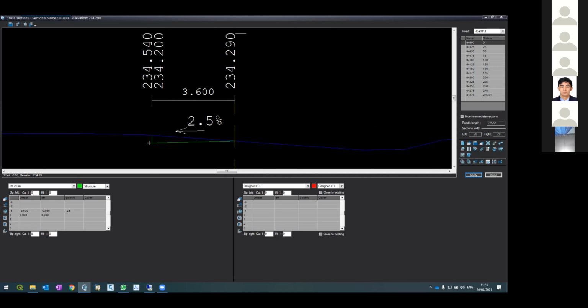From here, I want to create shoulders. Let's say my shoulders are one meter from here. Not asphalt, the soft shoulders, 1 meter. So I'm going to -2, and I'm entering -1, because I'm going, again, minus to the left, 1 additional meter.